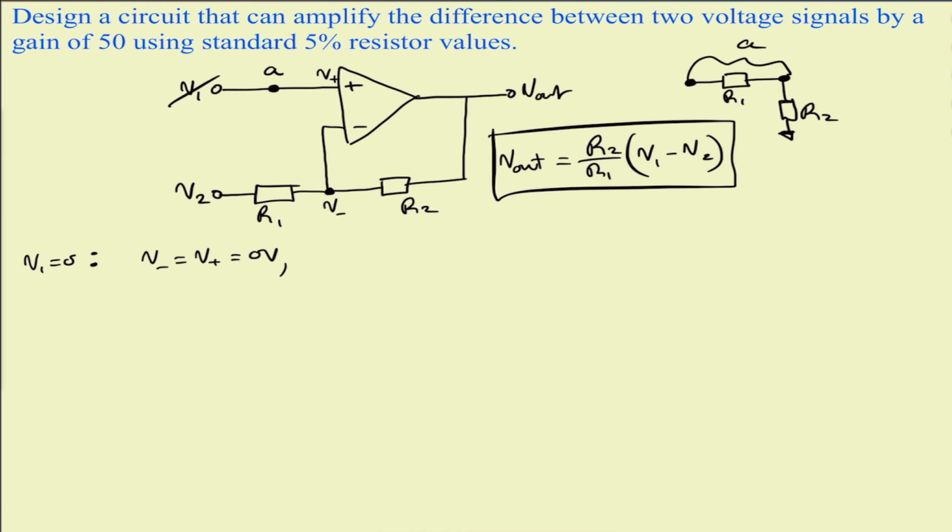So for this, if V out equals 0, we then have V minus. Let's now do it. I think we should go ahead and do it like that. So the voltage at V minus is equal to, in this case we set V out equal to 0, we then get R2 over R2 plus R1 with reference to V2.